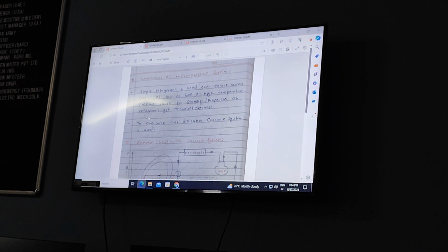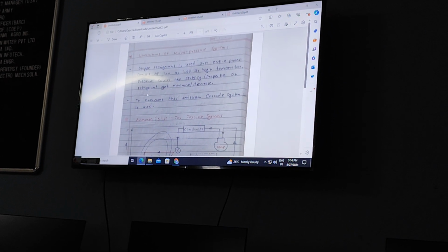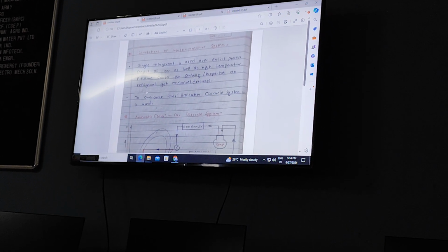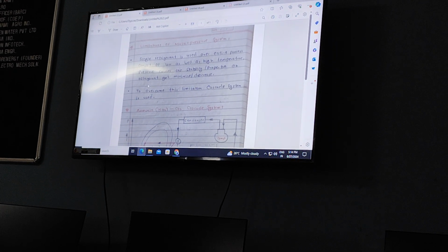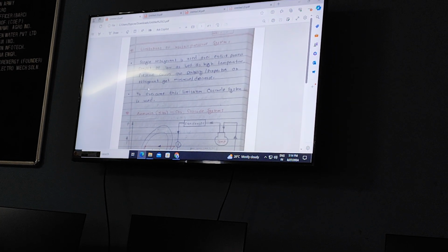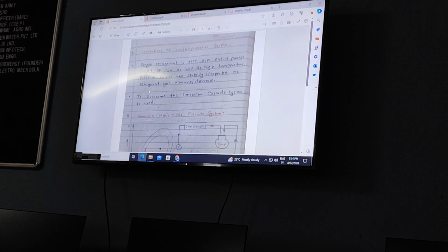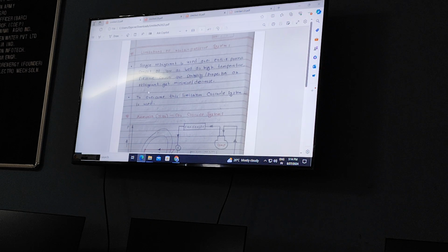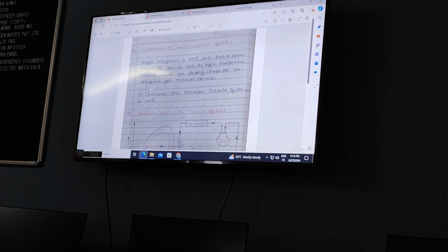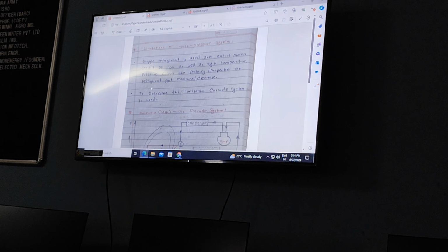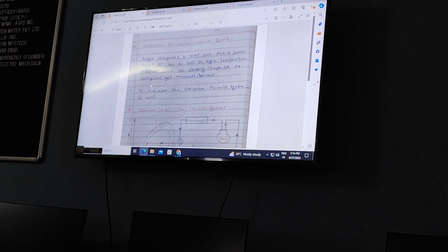See here. If we reduce temperature just by reducing the pressure, we can do it. You reduce the pressure again and again, then you will get the low temperature. But what is the problem here? Specific volume increases. Means what? The refrigerant requires more space, and its compressor work also increases. That's why we are going for the cascade system.